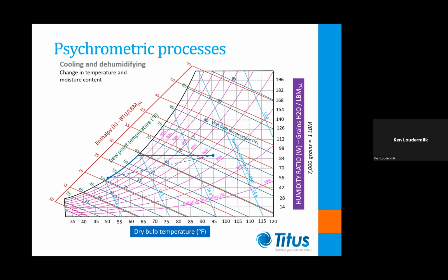Often, a diagonal line is used to illustrate this cooling and dehumidification process. The process results in a reduction of all the mixture's properties except relative humidity and density, which is the inverse of its specific volume.